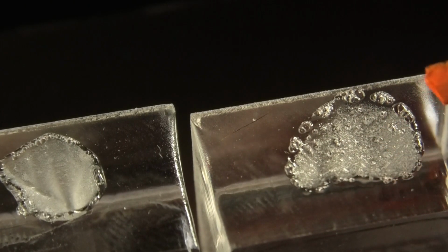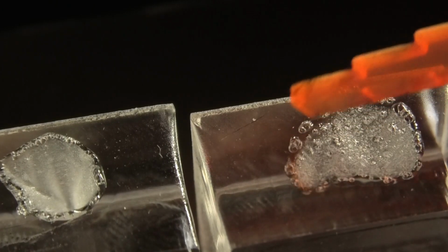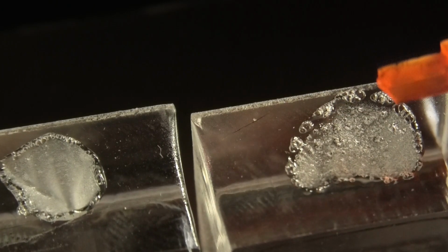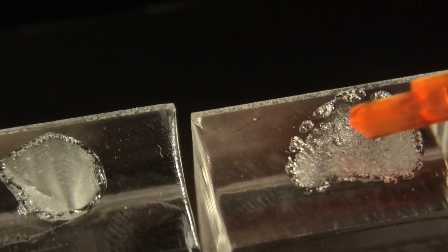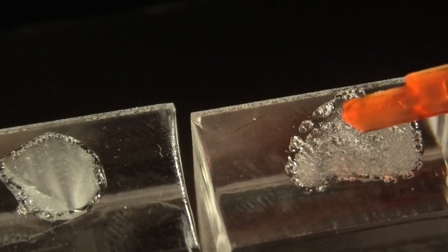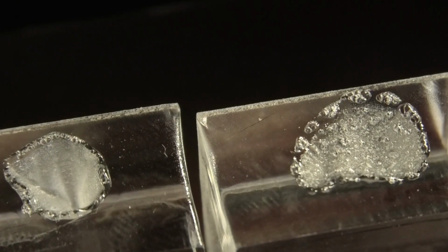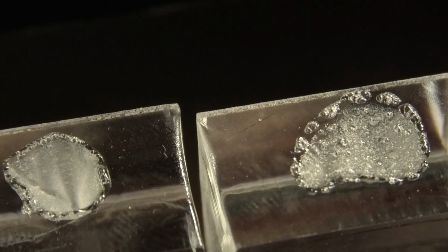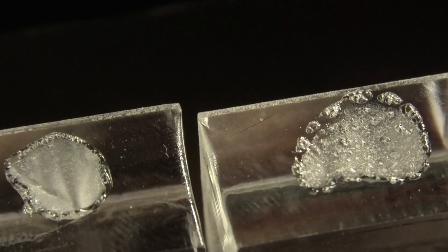And what you're seeing there, very low power, is causing the acrylic to boil, liquid boiling. You can see all these little dots around the outside, so there's little bits of power around the outside which are causing the boiling, but it's not enough to seriously evaporate it. Yes, there's a small depression there, and eventually it will make a hole. Whereas in this one, we've got such a high intensity pattern at the center of the beam, we're boiling and then evaporating away the acrylic liquid.